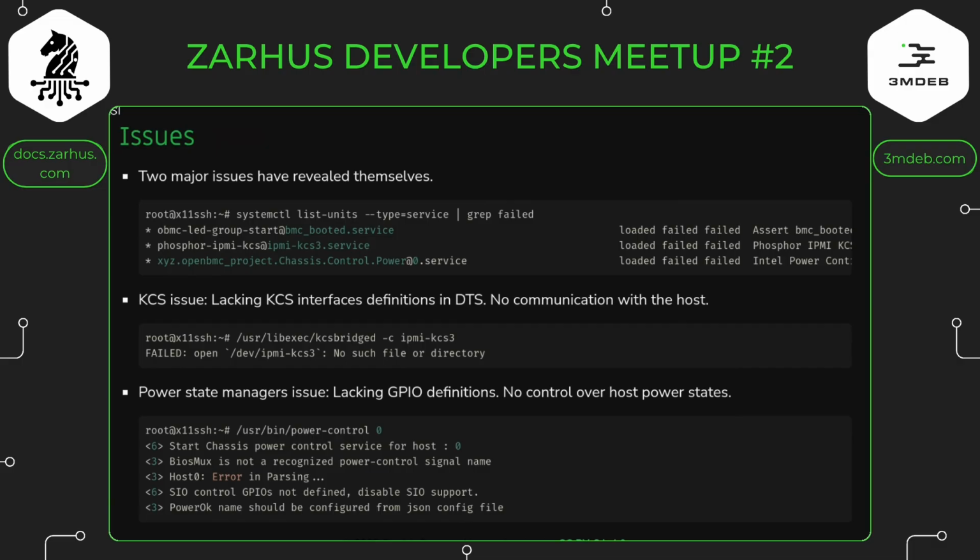Unlike the KCS addresses, each vendor can wire the SoC to their own liking. For KCS we are missing some addresses, but they are pretty standard among all the ASPEED BMCs. But for the GPIOs, the vendor can rewire the BMC however they want, and thus it is not something that you will find in the documentation of the BMC. We've got some definitions, but they are not sufficient.